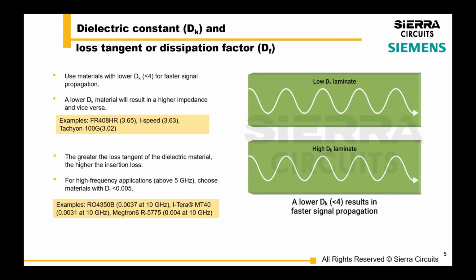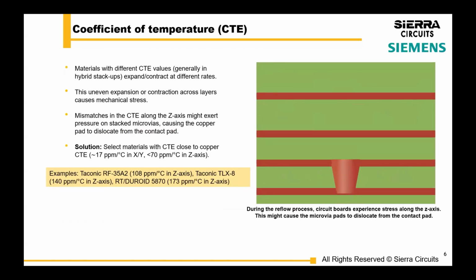Now, how your material performs versus the data sheet is different. So getting input from the fabricator, in terms of the impedance modeling and any kind of electrical performance, is a key thing. Not everything performs to the data sheets.